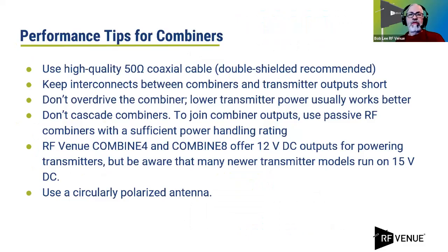So let's go on to performance tips. Okay, they're not appearing one at a time, but we'll work with that. Again, use high quality 50 ohm coax cable. Just like we said before, RG8X, really great. If you have to run longer lengths, there are lower loss cables as well, but it's not quite as critical for the transmitting side as it is for the receiving side.